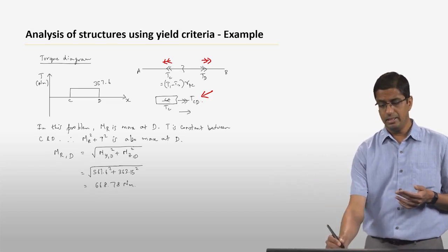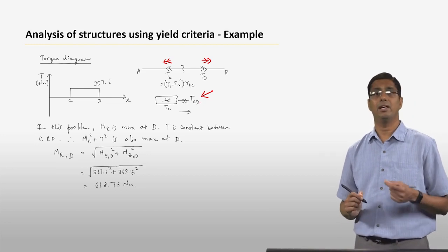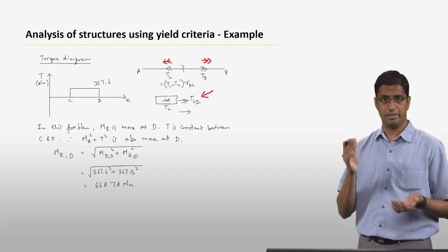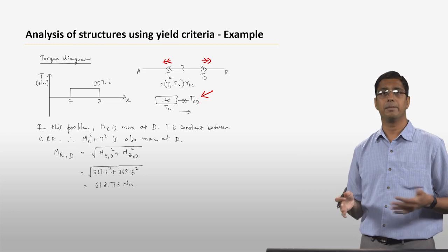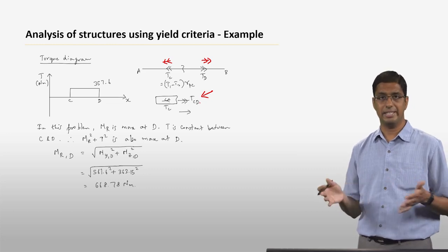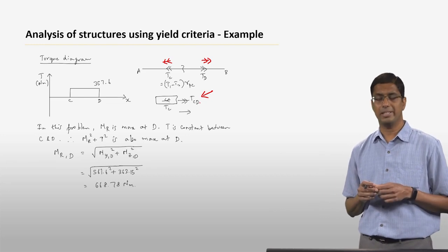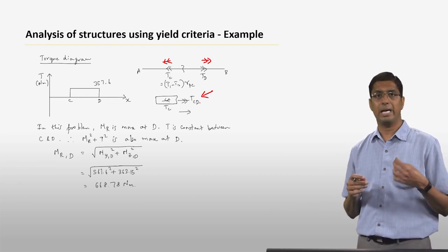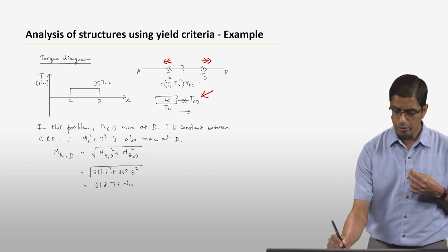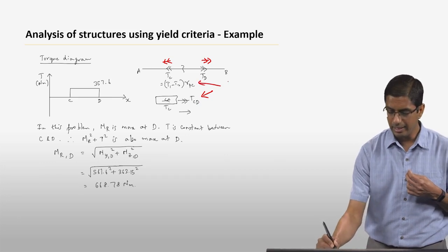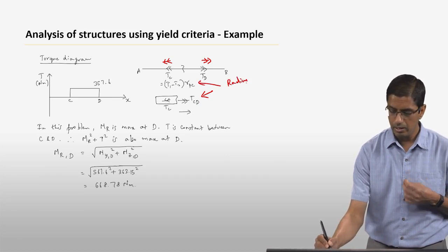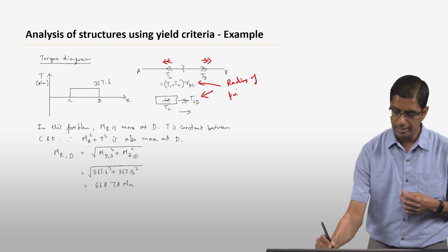And since the TCD is in the same direction as the outward normal to that cross section, that torque is considered positive. So the internal torque between C and D is considered positive. And this torque TCD is going to be nothing but T1 minus T2 times RPC, where RPC is the radius of pulley C.